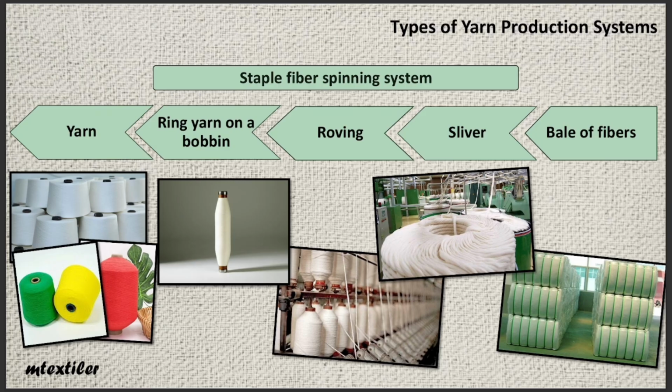In the roving frame machines, drafting occurs, and we obtain roving. A small amount of twist is applied to the roving to give slight strength. After that, in the ring spinning machine, rovings are drafted and twist is applied. The ring machine delivers yarn wound onto an empty cone. Because the yarn in this form is not yet directly usable, it enters the autoconer machine to both eliminate defects and provide excellent joining between the tail end of the previous ring frame bobbin and the head of the new ring frame bobbin, so that we avoid problems in subsequent processes.